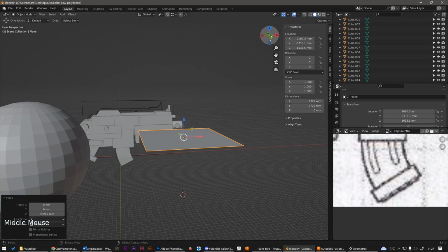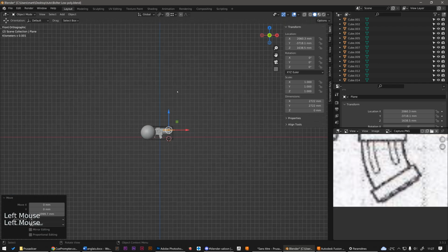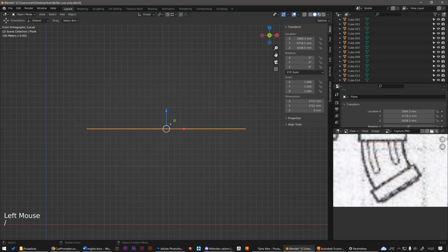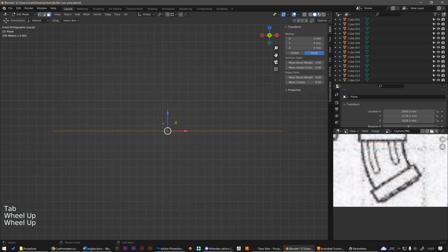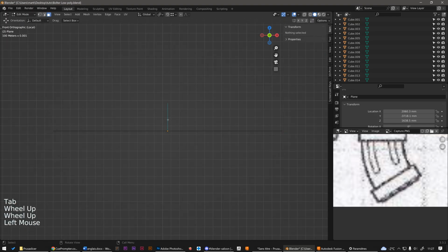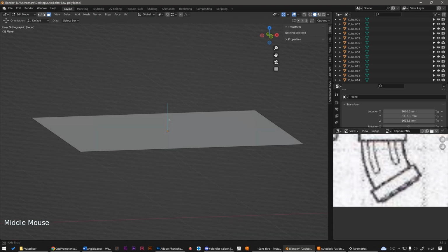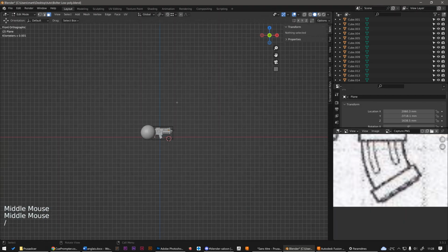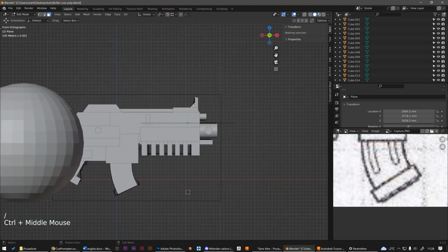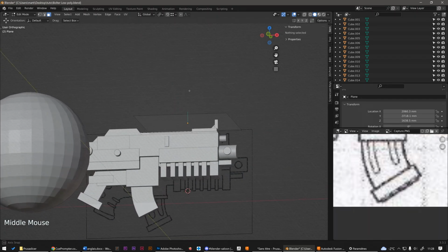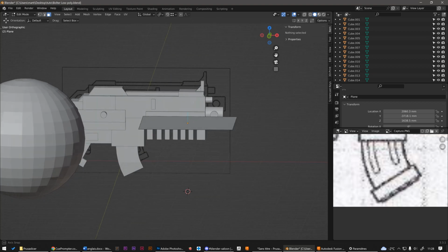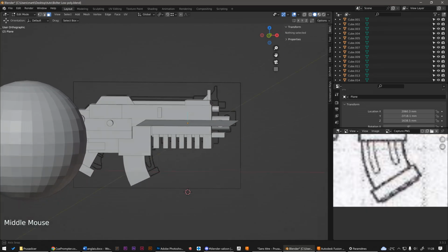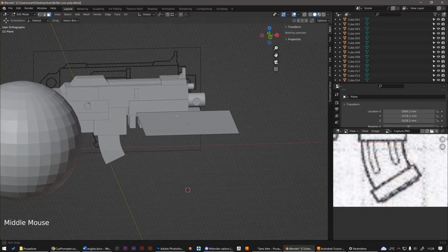And if I set a side view, isolate the object so we can see better, and switch to Edit mode to display normals, we can see that the normal is positioned on the visible side of the face. There, with other objects displayed, we can clearly see that the object is transparent from below, and from above, on the side where the normal is located, the face is visible.